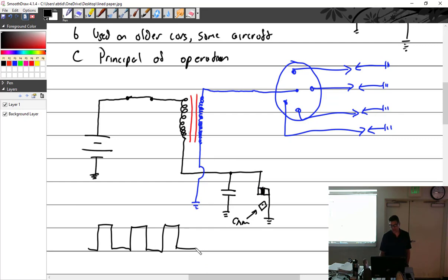And when you do that, every time you go on, you're moving across that secondary coil. Every time you turn it off, bam, snapping shut. And the way we're going to snap it shut is we're going to use a capacitor here. And so when those breaker points start to open, the capacitor, or condenser as it's called in these systems, same thing, is going to do a couple of things. And as I explained before, one, the electrons see that as an easier path.